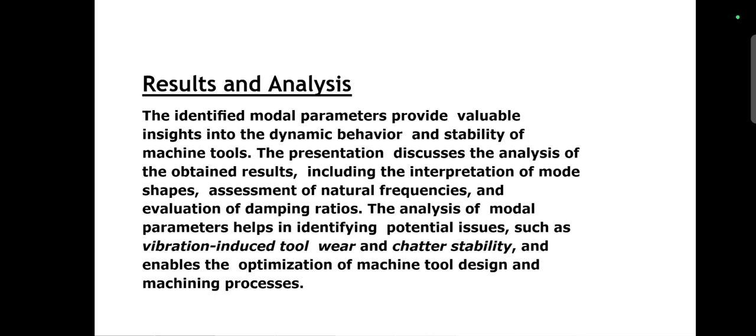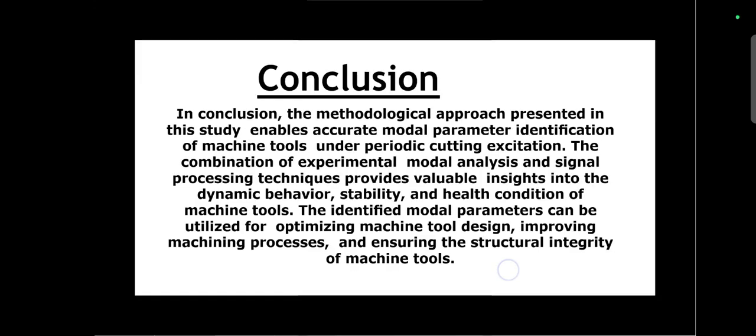The analysis of model parameters helps in identifying potential issues such as vibration-induced tool wear and chatter instability, and enables the optimization of machine tool design and machining process.